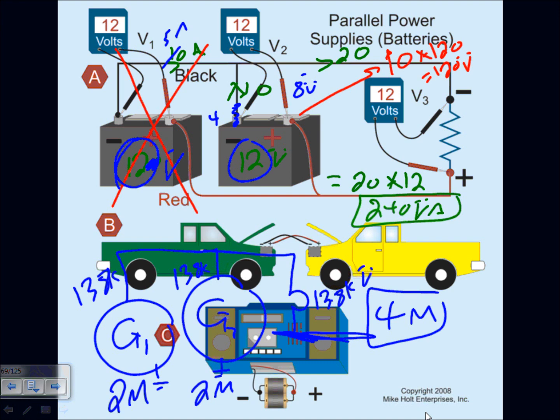I was thinking of pushing all these double amps to all your little fuses that are only rated for a certain amount. There are two types of currents in cars, and again, I'm not an expert in cars. One is the cranking, the one that starts the engine, which is a high amp current. It goes close to 600 amp at 12 volt. But for how long? Otherwise you burn it, right? For a very short amount of time. So your fuses are able to handle this amount of current for a very short amount of time.